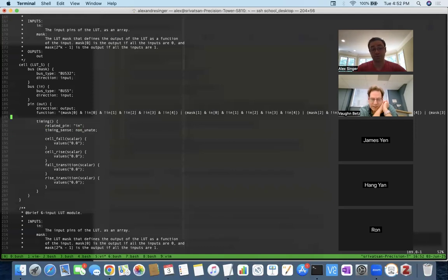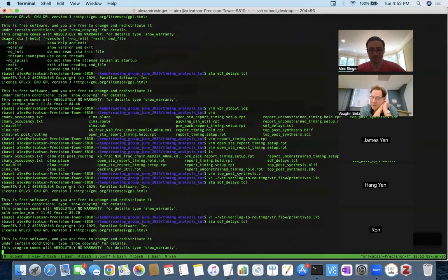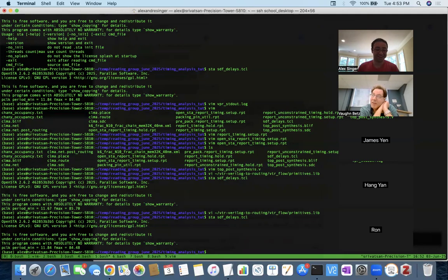I wonder if maybe it's correct. If that's true, then in that case, because we're providing the truth table here, I wonder if OpenSTA is smart. It might figure it out. Now, we don't actually mark different positive and negative delays, though, like rising and falling edges. If you had different rising and falling edge delays, then for sure you get a gain. Given that you're not doing that, it's not entirely clear to me where it got the gain from. Never mind. Maybe something in there is unate.